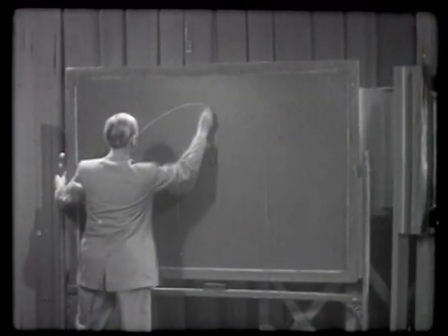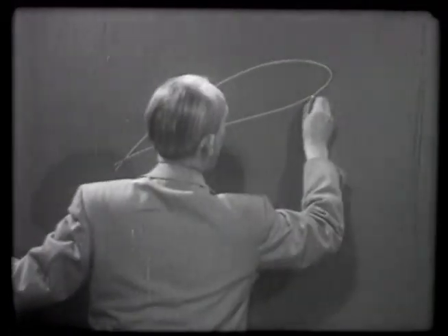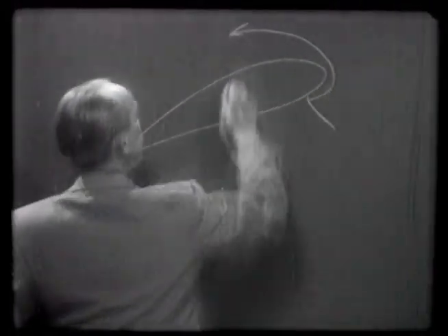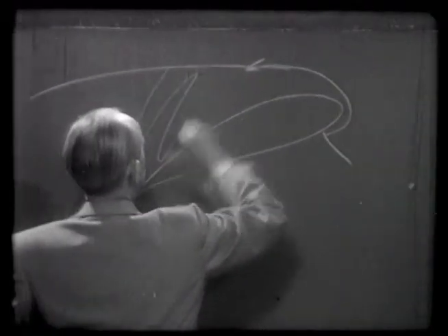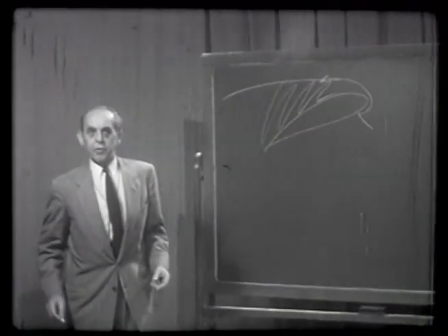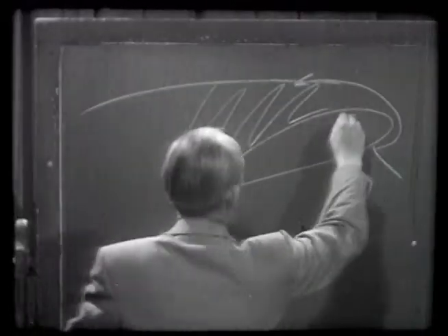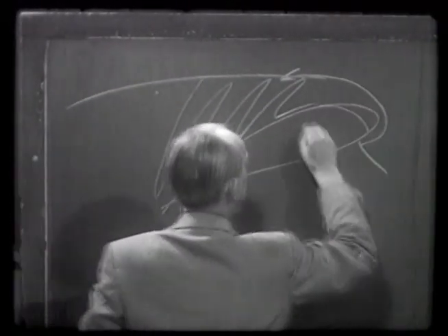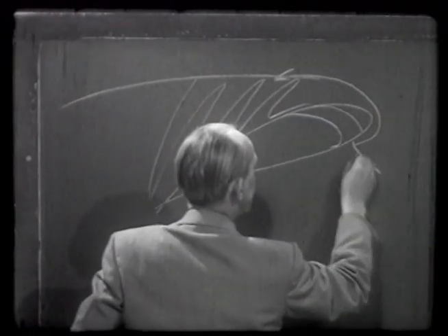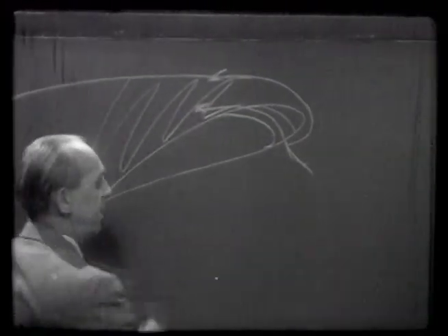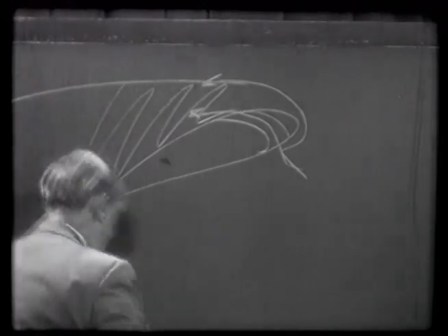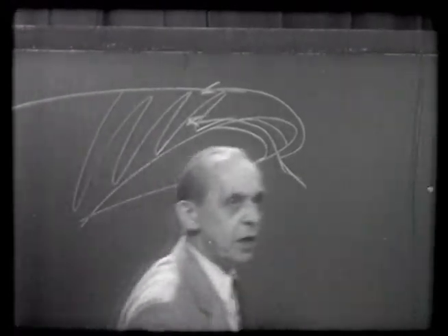We have this wing here, and the flow cannot go around here and stalls away. And this is a dead air zone. Now, to prevent this, what could we do? We could probably make a slot into the wing and let some of the air from underneath go into this dead air zone and blow it away.